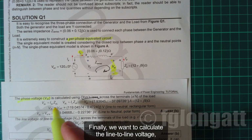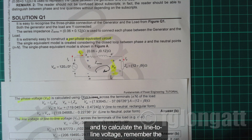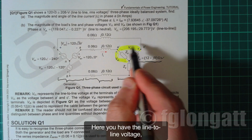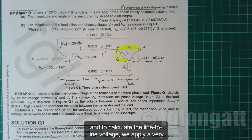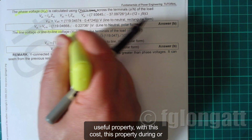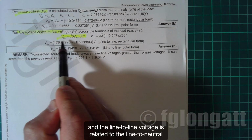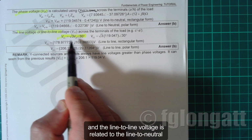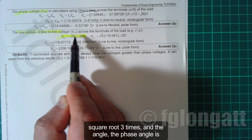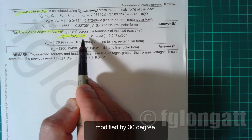Finally, we want to calculate the line-to-line voltage. And to calculate the line-to-line voltage, remember the line-to-line voltage is here in the main circuit. Here you have the line-to-line voltage. And to calculate it, we apply a very useful property. We discussed this property during our theoretical classes. The line-to-line voltage is related to the line-to-neutral voltage because the magnitude is amplified square root 3 times, and the phase angle is modified by 30 degrees.